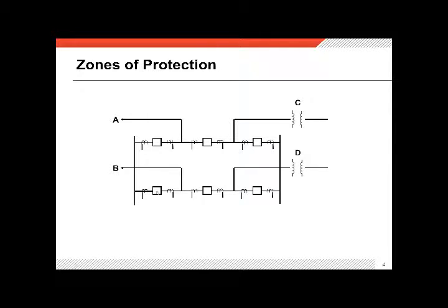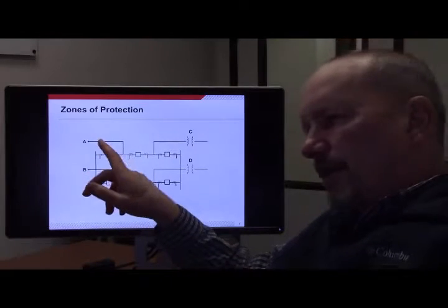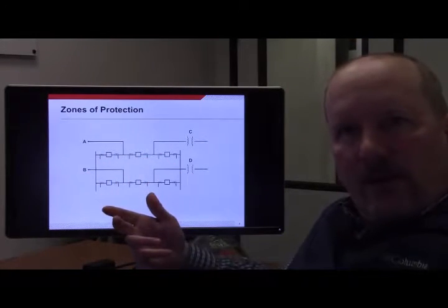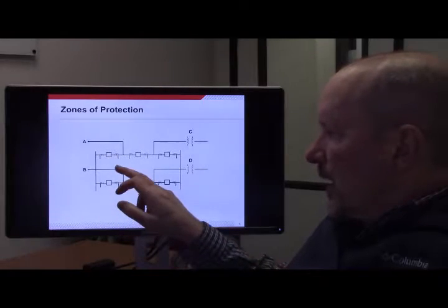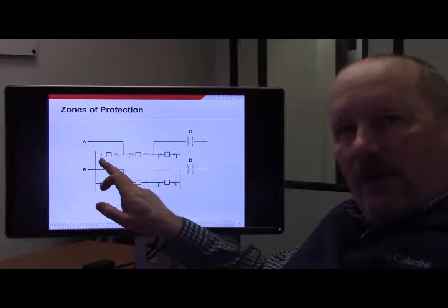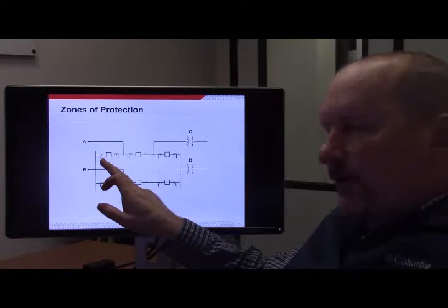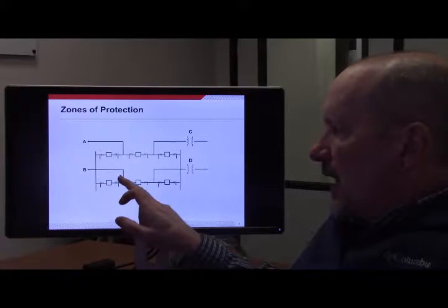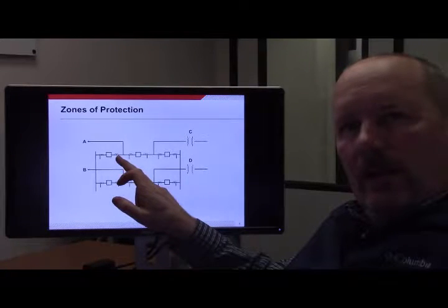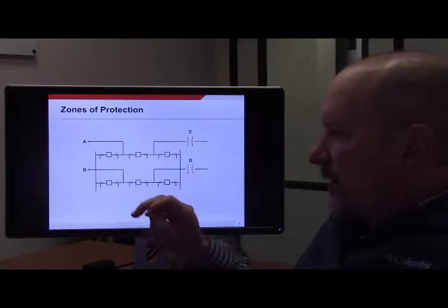Now then, I want you to think for a moment about what would happen if we were to not connect our CTs the right way. Say we put the bus differential on the outer CTs, and the line relaying on the CTs that are adjacent to the line.